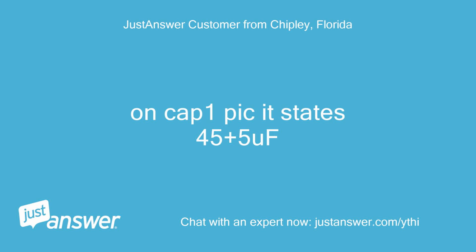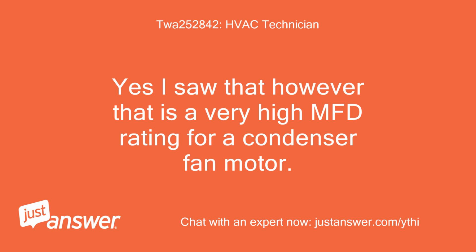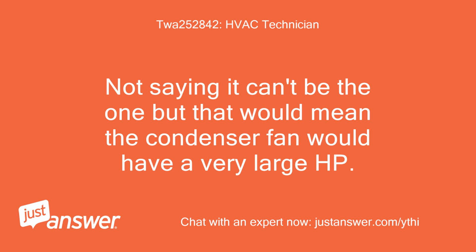On cap 1 pic it states 45 plus 5 MFD. Yes, I saw that, however that is a very high MFD rating for a condenser fan motor. Not saying it can't be the one, but that would mean the condenser fan would have a very large HP.